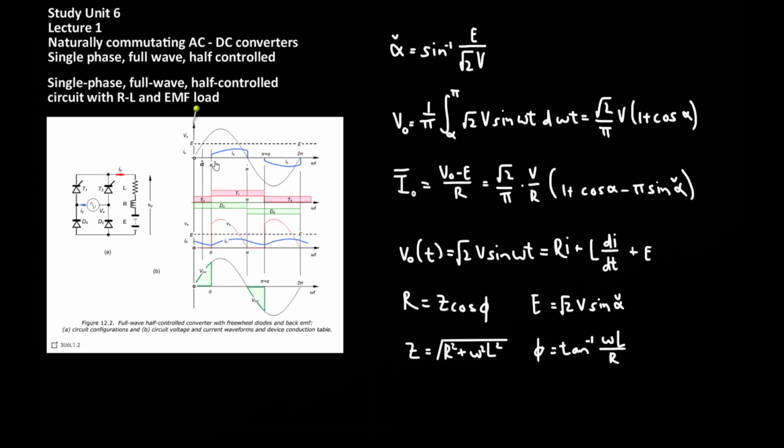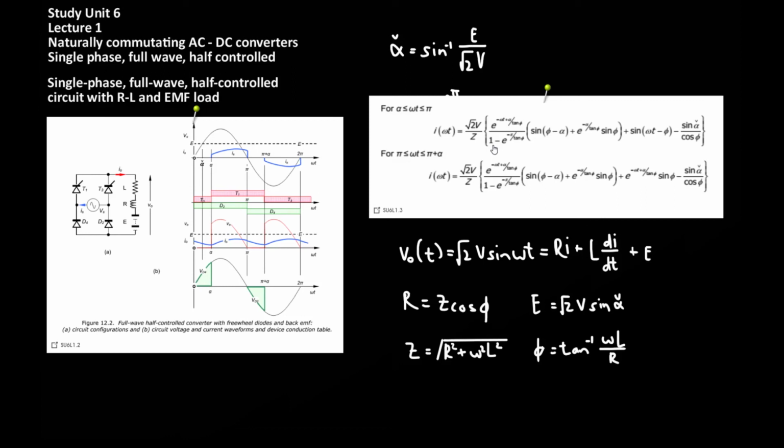In other words, depending on this angle, the delay angle of the converter, the output current function will change. To spare my handwriting, I've posted each of the expressions depending on what omega t is. Despite how intimidating these equations look, they basically just describe this periodic output current, which is shown graphically here.